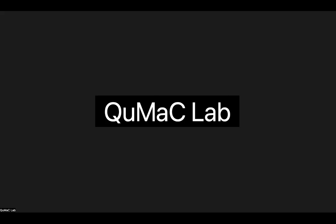Remember that I and Q are low frequency signals, usually going from DC to some finite frequency. So by choosing I and Q, you can create any amplitude or any phase of this signal at omega LO.